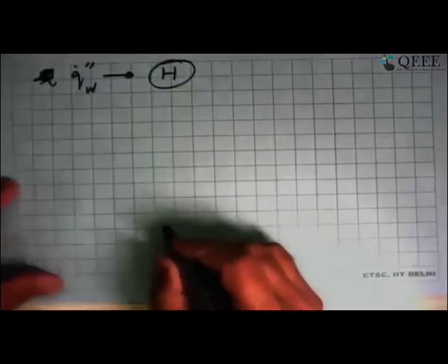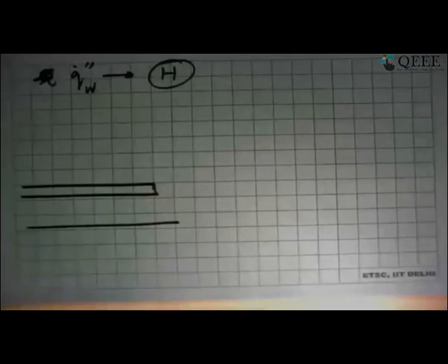And this happens when you look at the other counterpart of this, which is when q double dot prime at the wall is produced by, say, a constant heat flux case. And how do we get a heat flux case? It is very simple: if you have an electric heater immersed in this, for instance. So in the pool, we put in an electric heater, or we hold a small wire into the pool and say that this is the pool that we are looking at.